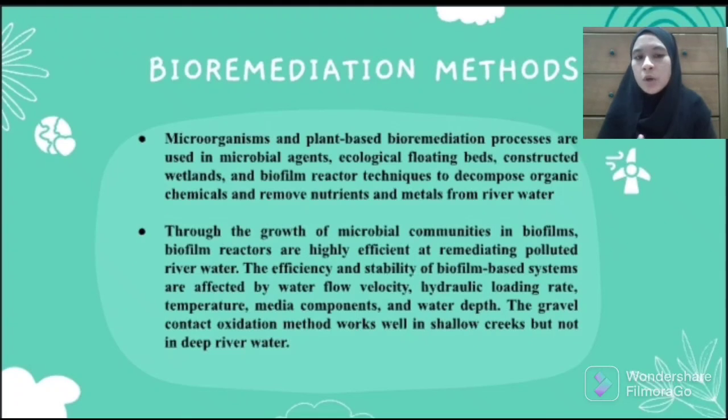Direct mixing of microbial agents with river water eliminates ammonia nitrogen, COD, and TP marginally. Engineering-based application of microbial agents breaks down organic matter and removes COD, BOD, and nutrients extensively.